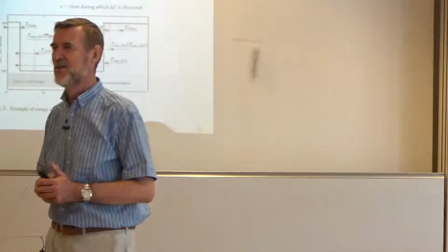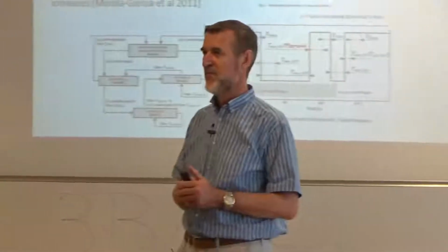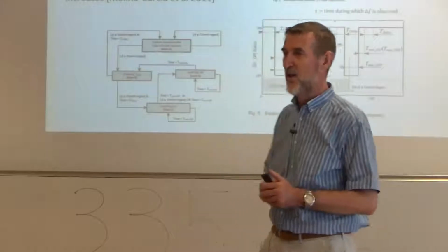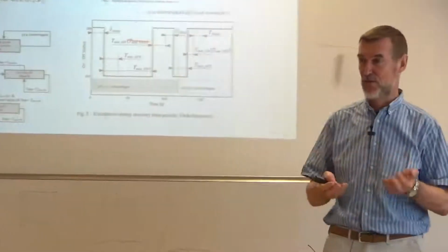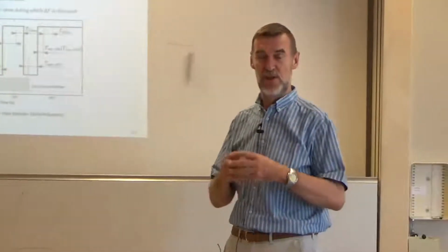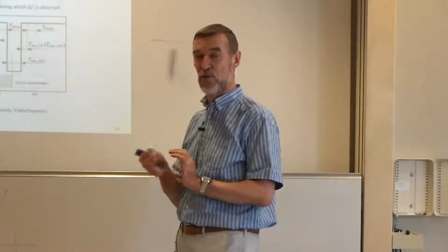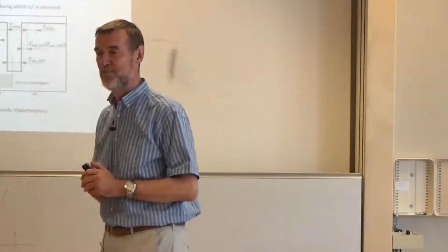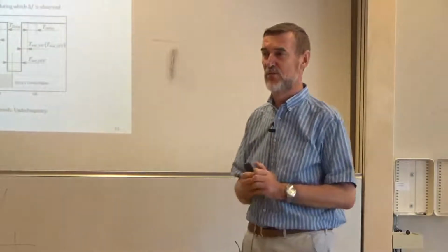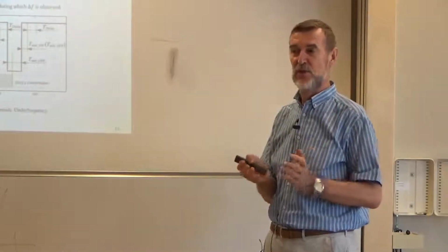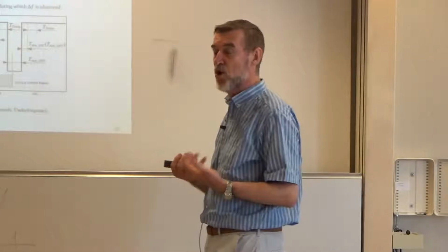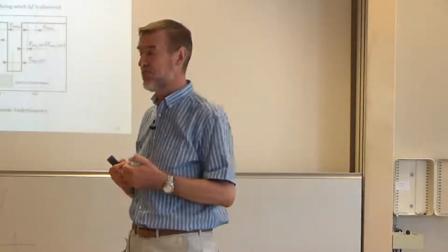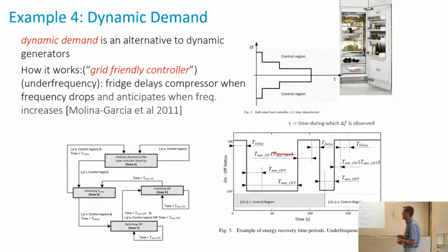Yes? Less inertia, less regional compensation. Exactly, less inertia. The system is smaller. Great Britain counts only on Great Britain in terms of inertia. Ireland is even worse. The Irish grid, which is one grid for Northern Ireland and the Republic, will be interesting after the Brexit what happens to it, by the way. It's an even smaller system. In a smaller system, the inertia is much less, and then the cost of reserves is very large compared to the other costs here. So this is why they are more sensitive to this.